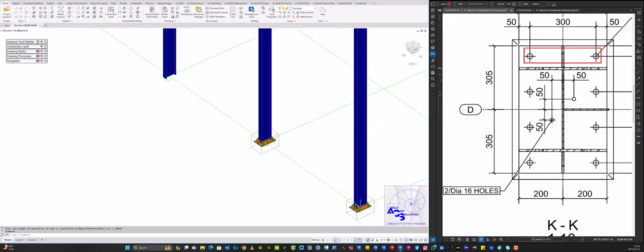So we're back there. Now, the other option of adding a connection is a bit lengthy. You go to your advanced L2 palette, and then you go to tools, which is the second option. We've got these two icons here, and then these other ones as well. If you put your mouse over, this one says joint copy, and this one says joint copy multiple.